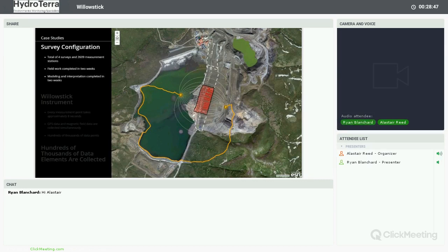So in other words, we energize the circuit and inject an electric current through the area. We use a signature frequency of 380 hertz. Now, the reason why we use 380 hertz is so we can filter out any noise which comes from power lines or anything else. 380 hertz is not a harmonic of 50 or 60 hertz, so we are able to detect that signature frequency. We call it our heartbeat signal.